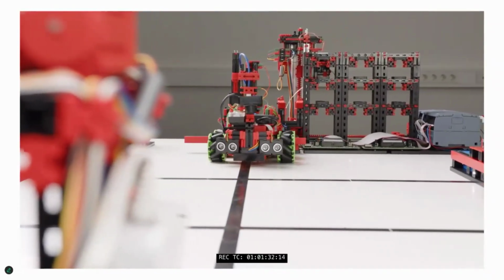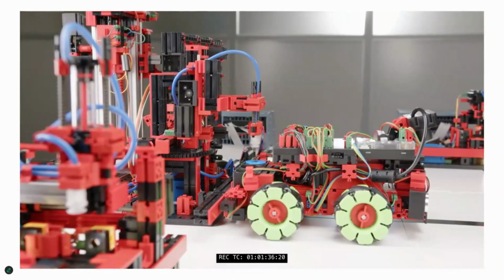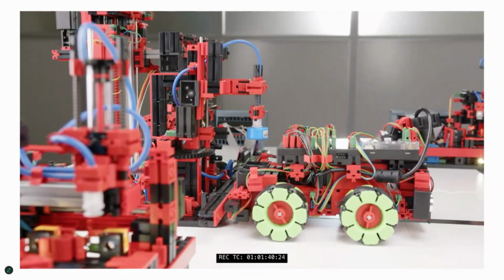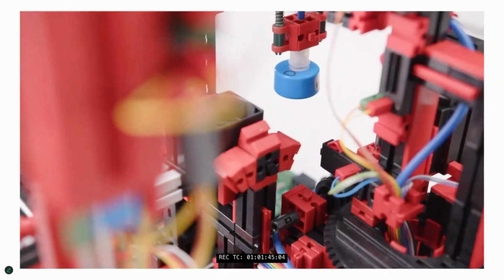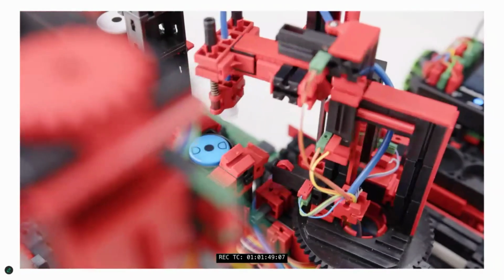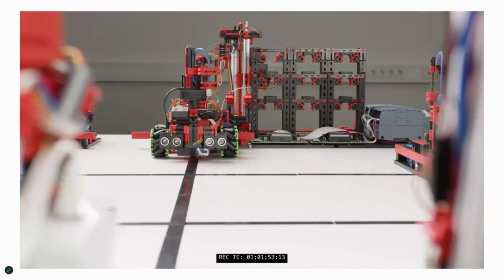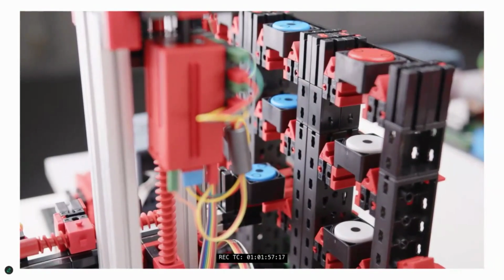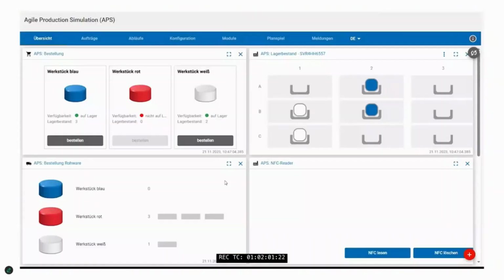In this case, just like the order of the description that we went through before, the AGV has gone first off to the automated high bay warehouse where the crane at that location picks up the workpiece, moves it into the carrier tray where it can be stored into one of the 9 slots that are available at the high bay warehouse. And again, things are retrieved in a first in, first out method.